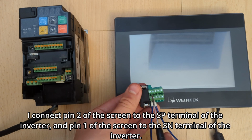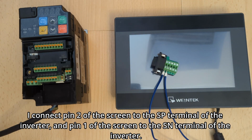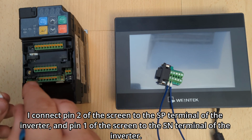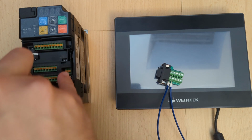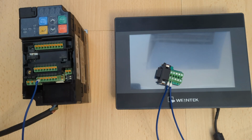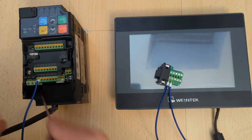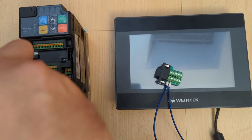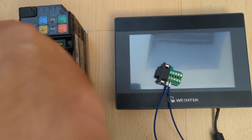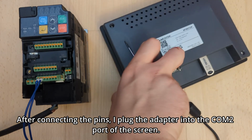I connect pin 2 of the screen to the SP terminal of the inverter, and pin 1 of the screen to the SN terminal of the inverter. After connecting the pins, I plug the adapter into the COM2 port of the screen.